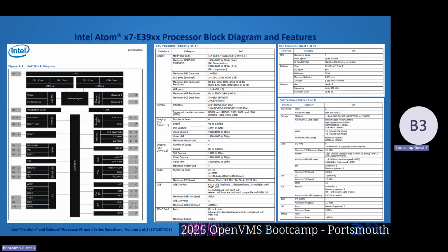You have an SD card. You have an eMMC card. You have these really neat ports called LPSS and LPC connectors. I'll tell you what those are in a second. ISH is another type of device that can go out and talk to real-world devices. You have the SM bus, which is a system messaging bus. And there's a slight difference between the SM bus and the PMC. And there's another interface out here that the CPU uses to talk to all of its internal components called a primary to sideband bus, P2SB, which Intel goes to great lengths to hide from you.